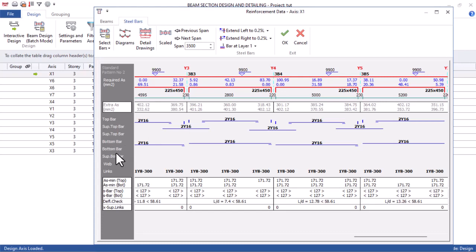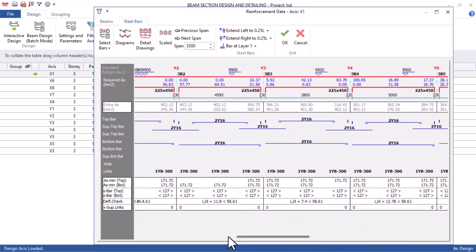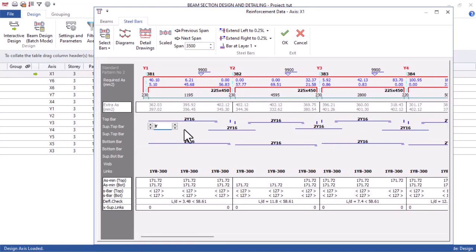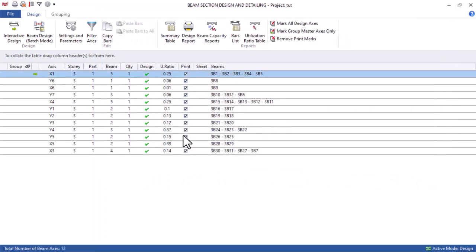Looking at this, this is your bottom reinforcement, and this is your bottom bar and your bottom support, and the link is the stirrup member. So you can see it's telling you should put both 2 and 2 at the bottom. So this design is okay. I think at the roof you don't really have much impact. So we can go on to the other beams on the first floor and the second floor, where we have the slab load distribution down to the beam. So let's go.